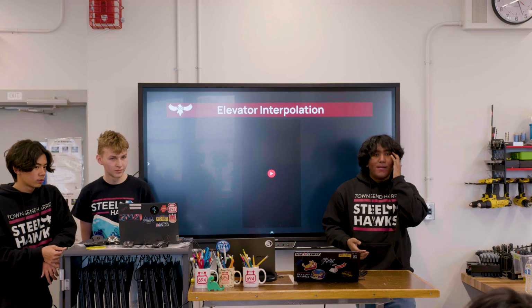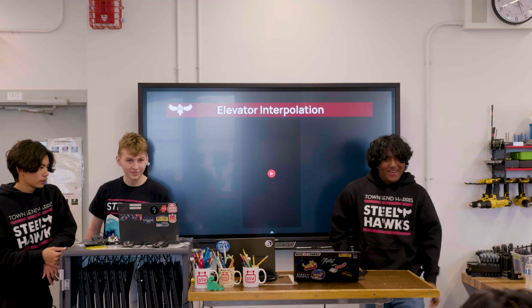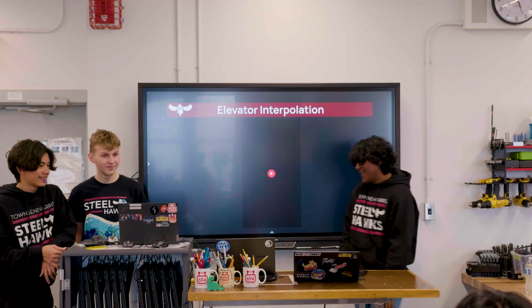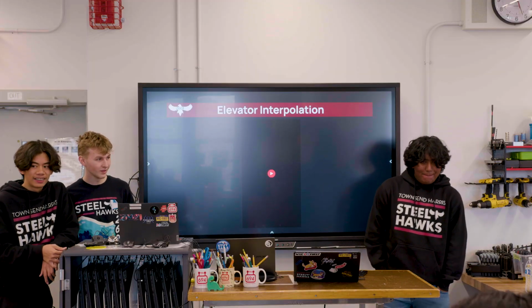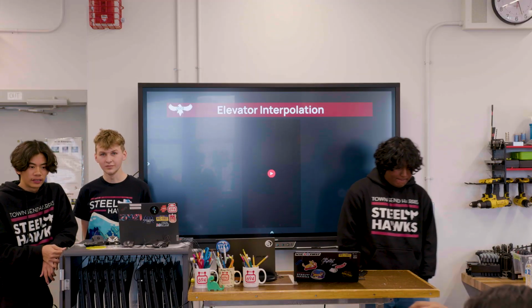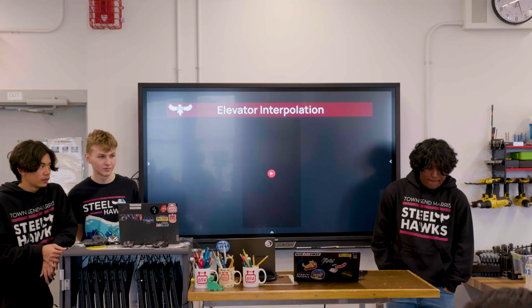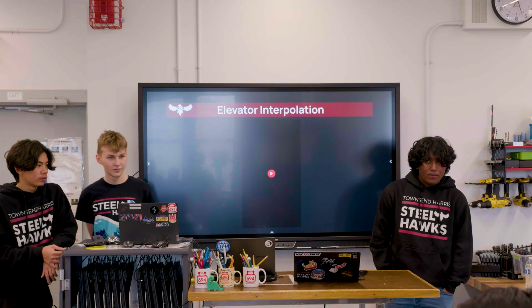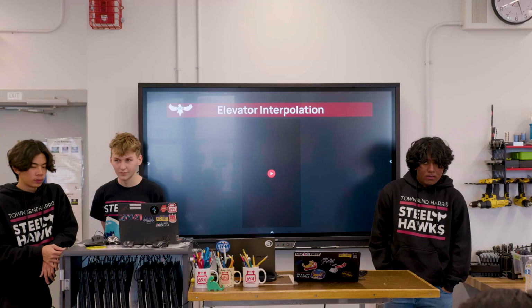Can I explain? You could explain. Okay, so vision basically uses AprilTags to see where you are, but odometry uses the movement of the wheels, based on the current starting position, to see where the offset is. That's good. That's what I assumed it was, but I explained it.